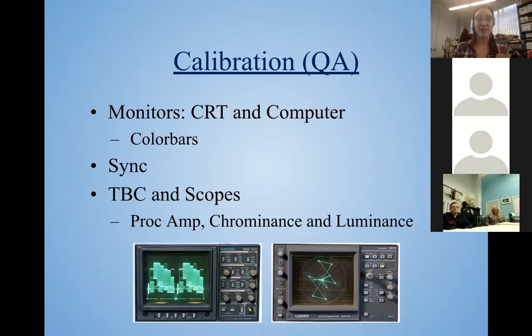There's also this other aspect of sync. So making sure that there are these synchronizing pulses that are actually stored. Remember the first slide I showed you for video that was just meant to overwhelm you? There are sync pulses within the video signal to keep everything synced, so nothing gets out of alignment. You don't have audio that's 1 second later than your moving mouth. Those are other aspects that you can calibrate and look at through your scopes and through external devices that can send out a synchronizing pulse to sync everything within your video rack.